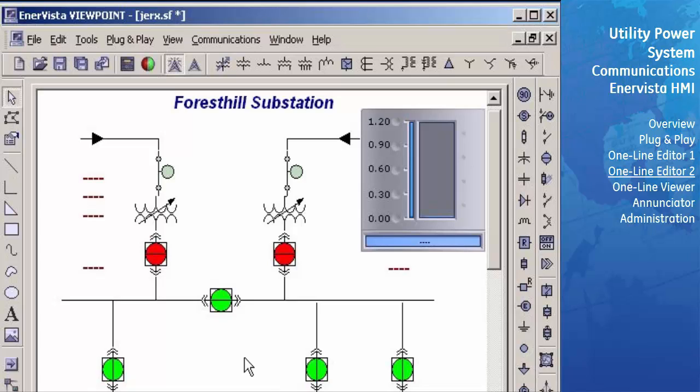We will now conduct a general test to see if our schema's monitored components are connected and configured properly. The system editor command we will be using is the one-shot test. The one-shot test is designed to perform a one-time poll of analog and digital values from actual devices that we have configured, and then to display those values on our schema in the system editor. It does not, however, validate whether or not our control components are set up properly. To check our control components, we'll have to use the System Viewer.